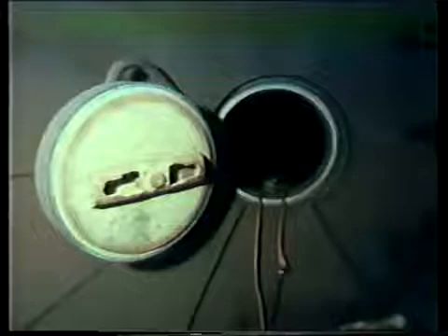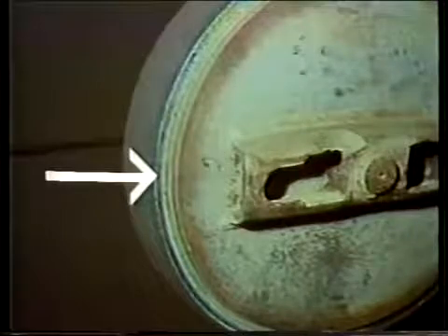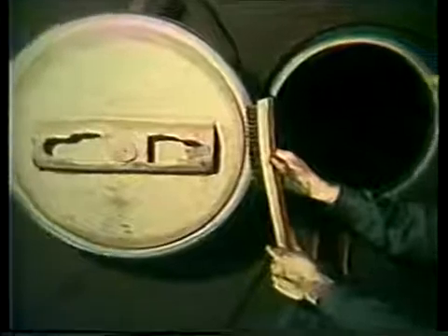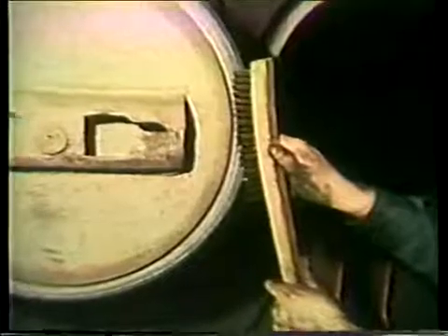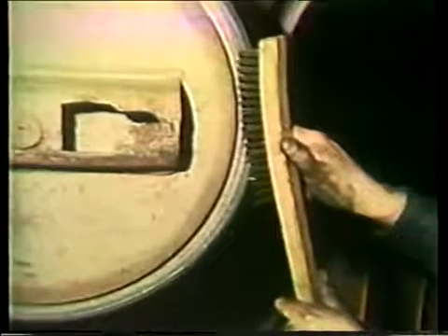Manways are also inspected closely. Here, be sure to look carefully at the sealed surfaces on the manway plates and vessel. To do this correctly, before inspecting, clean the surfaces with a wire brush. Also, look for gouges and nicks or cracks in the sealed surfaces.